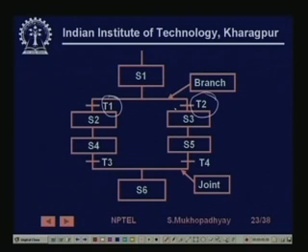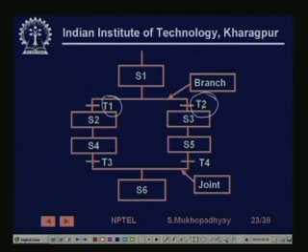It could conceivably also happen that in a given scan T1 and T2 both become true. In that case you have to resolve, because both transitions cannot take place simultaneously. There is a convention that the leftmost transition takes place. So if T1 and T2 are true at the same time, T1 is assumed to have taken place.